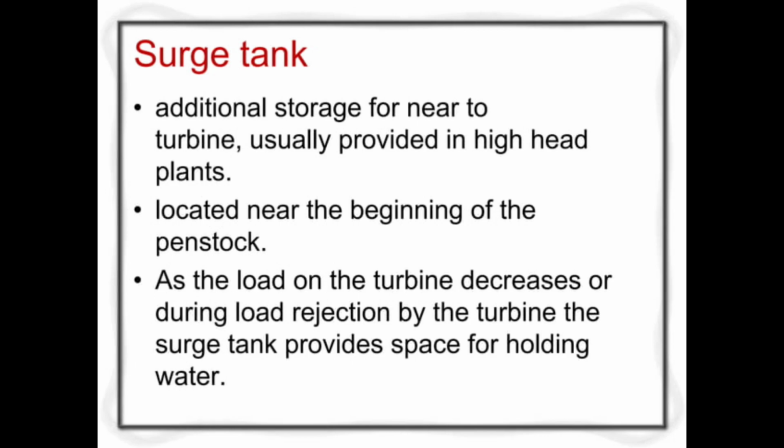Surge tank. Additional storage near the turbine, usually provided in high head plants. Located near the beginning of the penstock. As the load on the turbine decreases, or during load rejection by the turbine, the surge tank provides space for holding water.